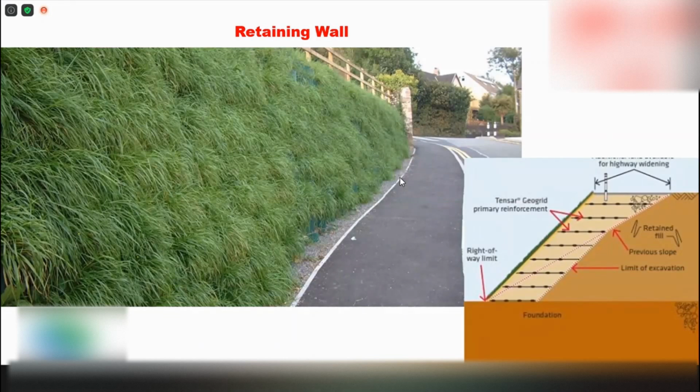To separate the two-layer road, because of the level, there needs to be an embankment. In a conventional way this embankment will be an RC retaining wall, which will be very ugly. But with the use of geogrid reinforcement, we can build a very beautiful green wall. After it's built, grass grows on it, and you hardly realize that there's a retaining wall there. That's the beauty and the magic of using geogrid to build retaining walls in this manner.